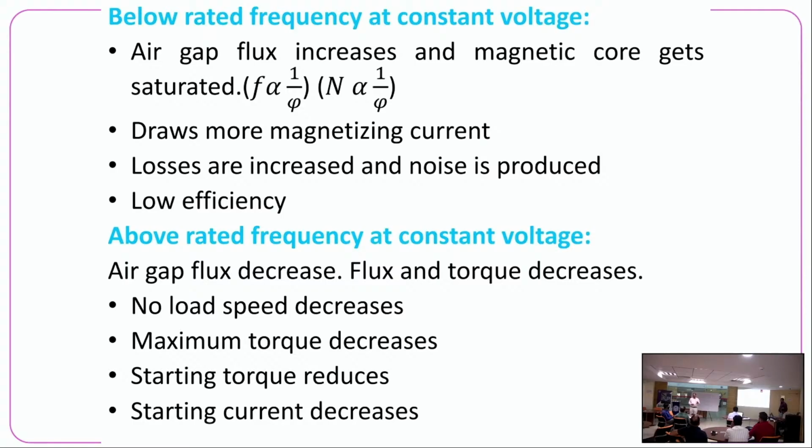Suppose we have reduced the frequency from 50 Hz to 20 Hz, then the voltage should also be reduced proportionately from 400 volt. So flux should be constant. Okay, we will take a break and after that we'll continue.